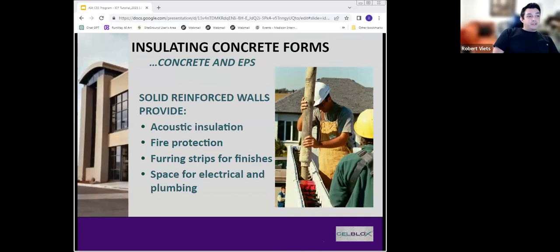So those are the two main ingredients of an ICF wall. You can see in the picture here, this is what it looks like as we're building it. The ICF blocks themselves are kind of like a big Lego block. You stack them up together, form up your whole wall structure, form out your building. Then when you have everything in the shape of the building that you want, you fill it up with concrete from the top, and the ICF blocks stay on, though. You don't break them off. They start off as your form, and then they become your permanent insulation after you're done pouring.